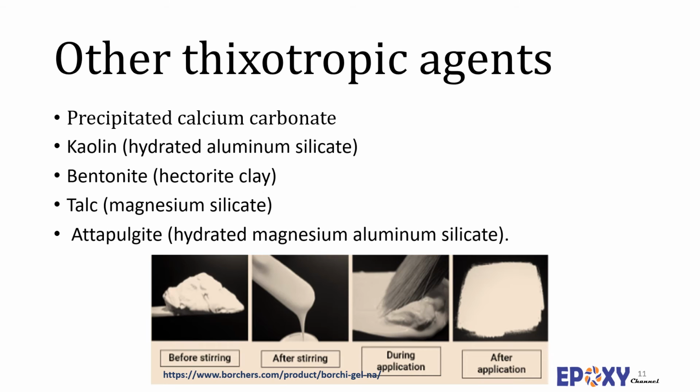The finer particles of kaolin occur as platelets, and the coarser particles form stacks or books of platelets. Kaolin is relatively soft and it is non-abrasive. Here again, the key parameters in choosing a particular grade are, for example, particle size, shape, and particle distribution. Kaolin is also available in hydrous and calcined grades. Special surface modifications are available to further improve reinforcement.